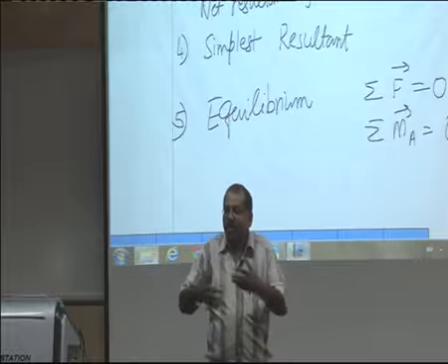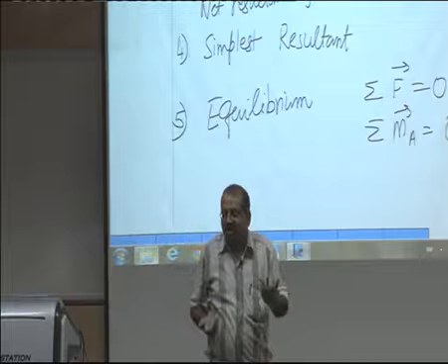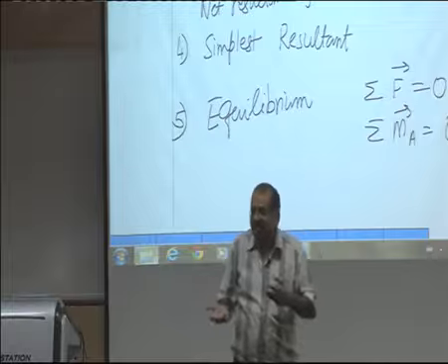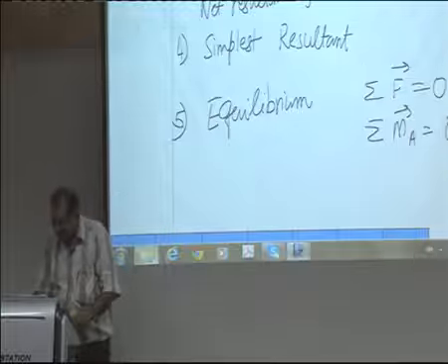I personally don't find it very convenient to use three force, because then you have to locate the point where the three forces are intersecting, and that is as much work as doing sigma Fx is equal to 0 and sigma Fy is equal to 0.